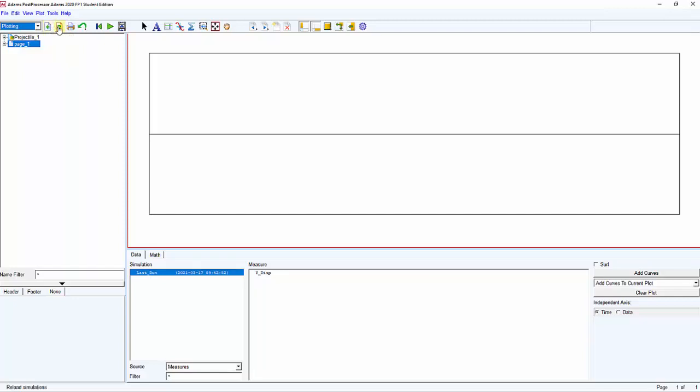This one is very important, which is basically if you are running a simulation, the results that will appear in the plot will not be updated by itself. If you changed something in the model, or you changed something in the simulation parameters, or you changed parameters in your components and did a new simulation, you can reload the new results. Reloading the new results is going to update the plots for you.